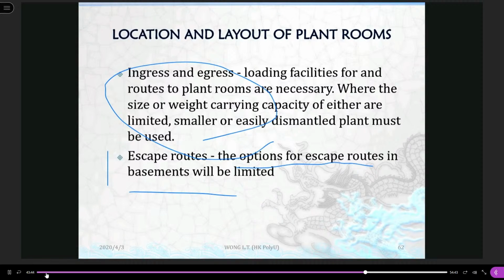The access goes through the floor slab. For the basement, there is a floor space allowed without any permanent shops over there. If maintenance requires replacing the transformer, they demolish part of the floors, a block, so there's a hole from the ground floor down to basement 3. Therefore, with this example I'd like to illustrate that basements are quite difficult to access, so we need more effort to design the escape routes as well as the maintenance space.